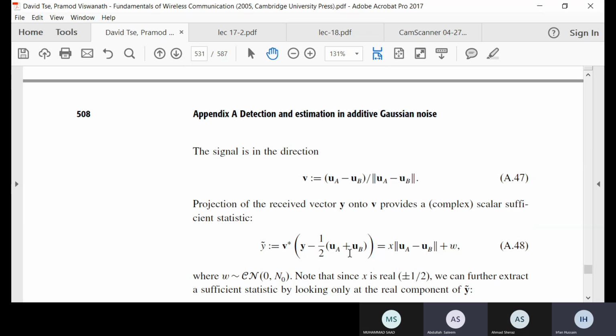So what I will do, the same thing. I will subtract the mean, project this onto the receive signal direction, which now I will take complex conjugate. Previously it was transposed. Now because it is complex, I have to take complex conjugate, and I do this multiplication.